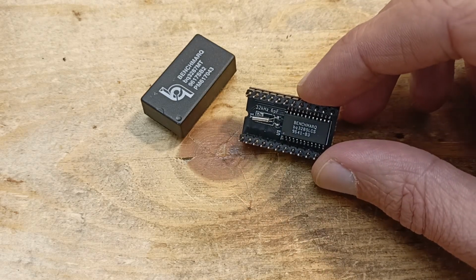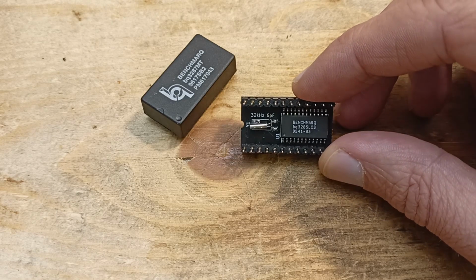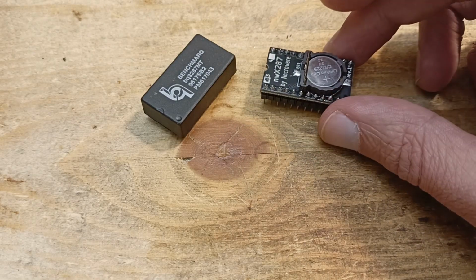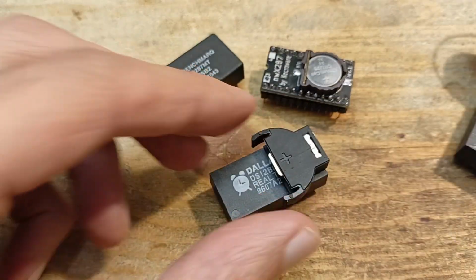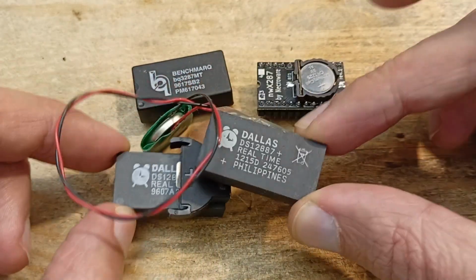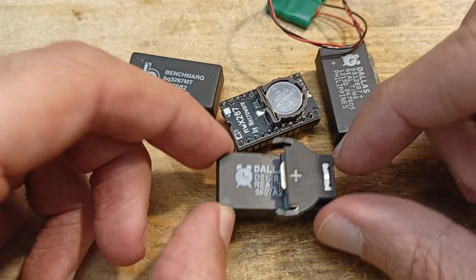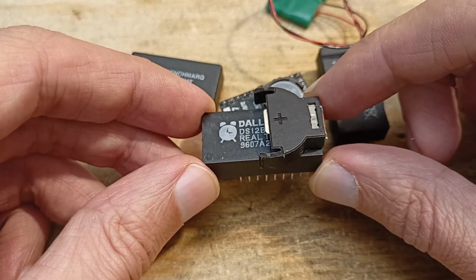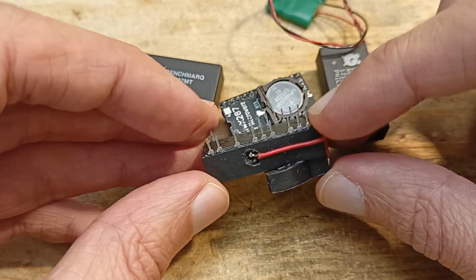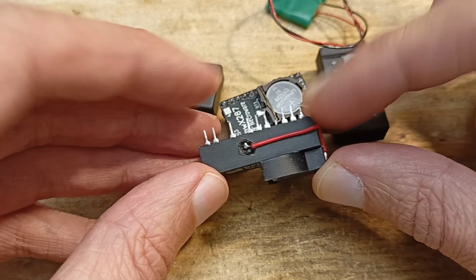Anyway, now we are facing the next problem. Meanwhile, the required BQ3285 ICs are mostly sold out everywhere. I have some in my personal stock, but not many, and so on some boards I started to come back to the old solution, which I presented before I made my own module. The solution is quite simple. Drill a hole in the housing of the module at the right spot to reach the pad of the internal battery. Solder a wire and a battery holder for an external battery and you are done.